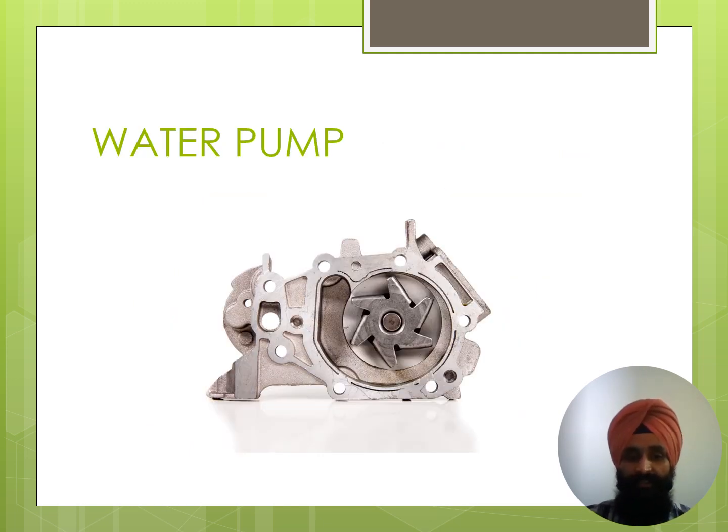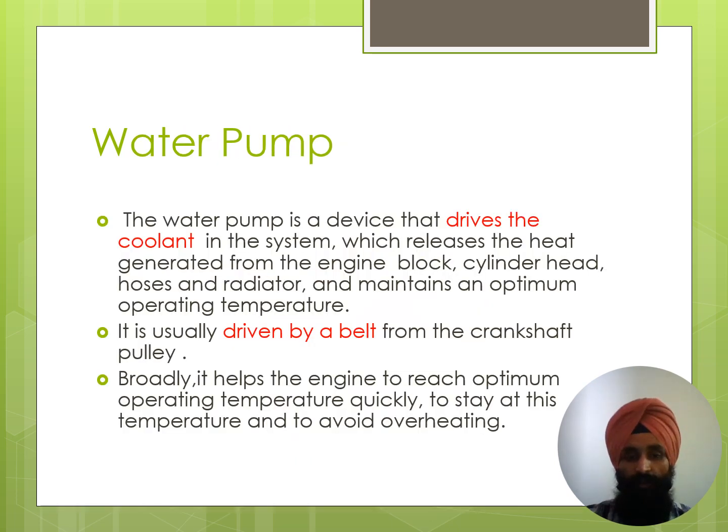Next, students, is the water pump. As you can see, this is a water pump. You must have a question: what is the purpose of the water pump? The water pump is a device that drives the coolant in the system, which releases the heat generated from the engine. Now what is the coolant? Coolant is used to remove the heat generated in the engine block.